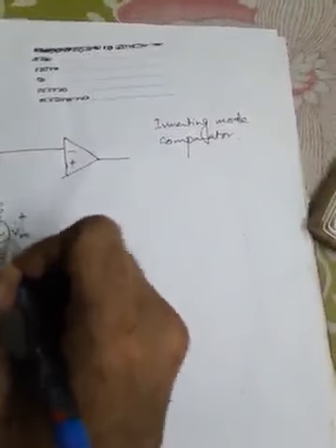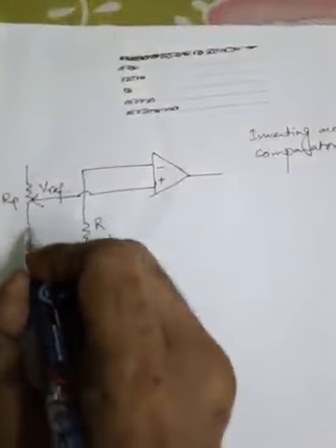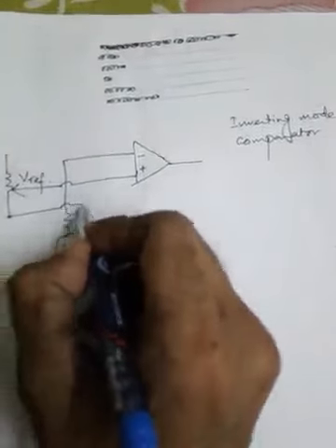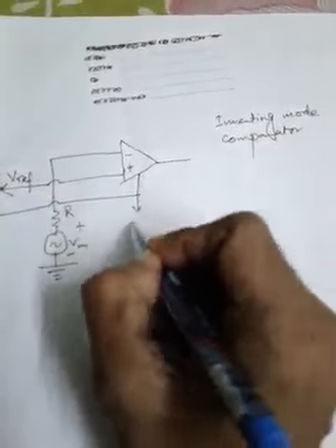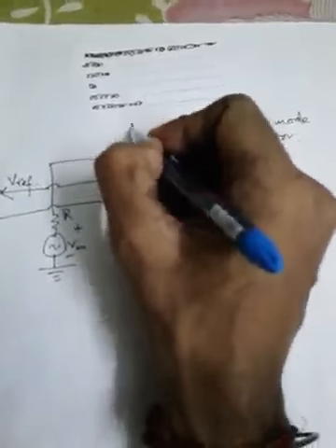So this is Vin through R. It is connected to the inverting terminal, and at the non-inverting terminal it is connected to a variable resistance in this way. So this is producing the V reference voltage, and this is RP, the potentiometric resistance or the variable resistance denoted by RP, and this resistance is connected to minus VE in one direction and plus VCC in another direction.